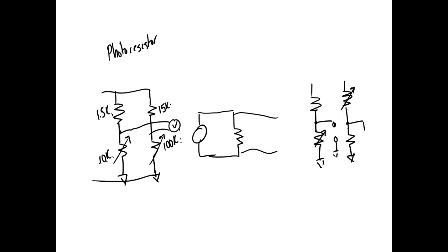It's real easy to get a 0 in centigrade because I can just take my sensor and immerse it in a glass of ice water, right? And then stir it up real good and put my sensor in there, and that would give me a reference of 0. If I did it on the Fahrenheit scale, somehow I'd have to get what? 32 degrees below, I'd have to go to 0, and that would be a little harder.